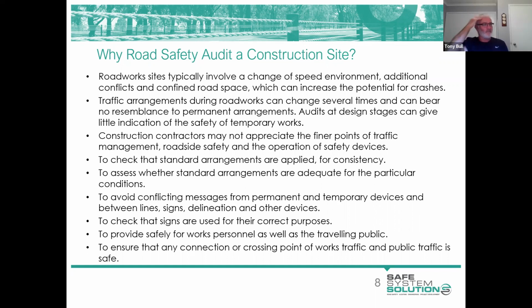Whatever it might be, we might be doing a contraflow. Make sure all that signing for the normal lanes in one direction are taken down or covered to allow for that new contraflow setup. So you've just got to make sure that there aren't any conflicting messages or signs or line marking that can cause a conflict point.